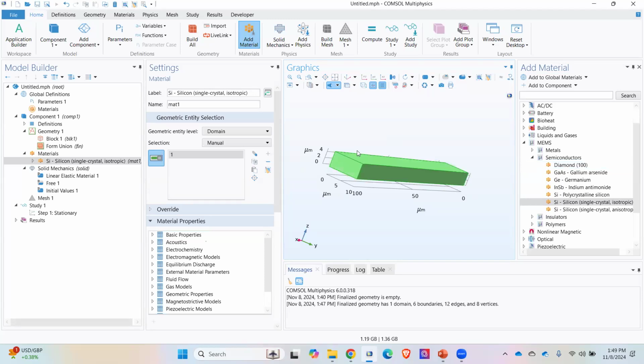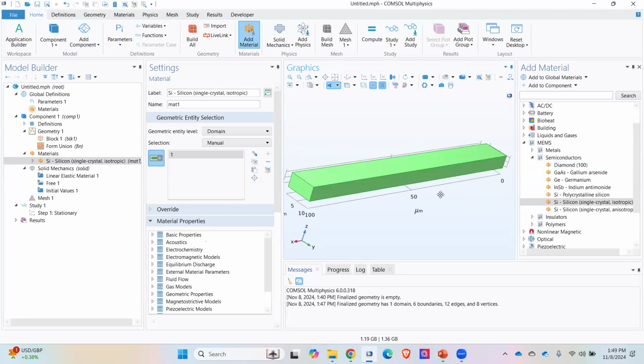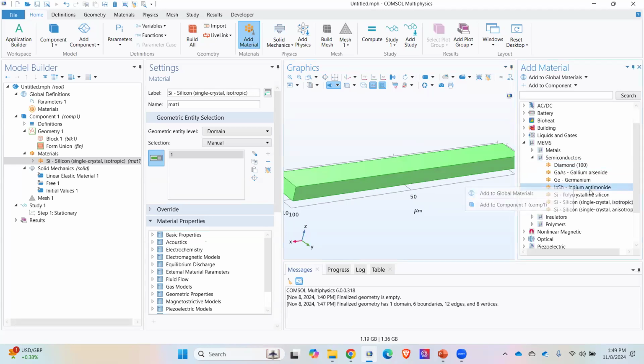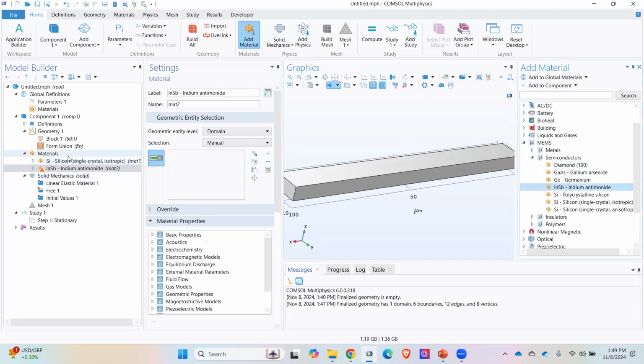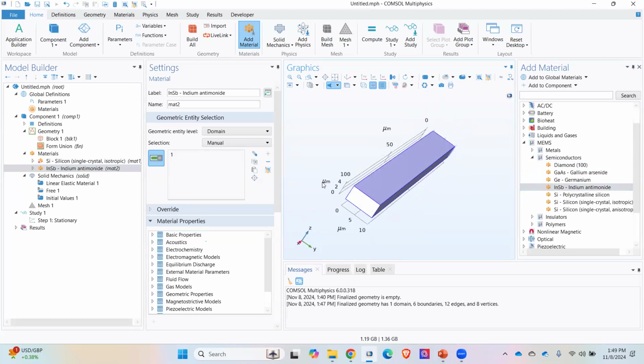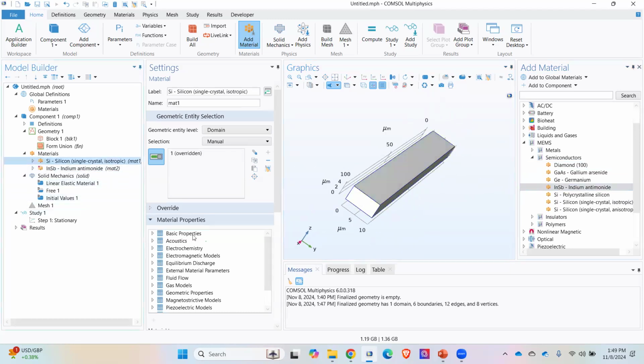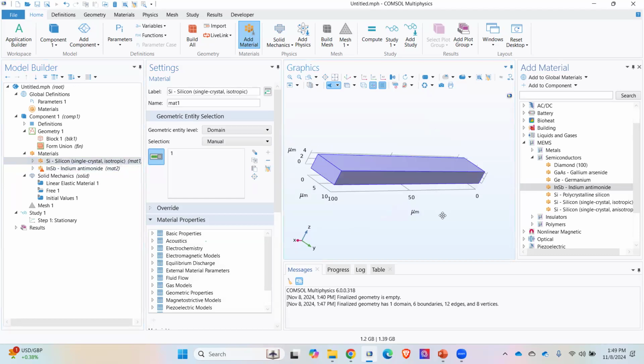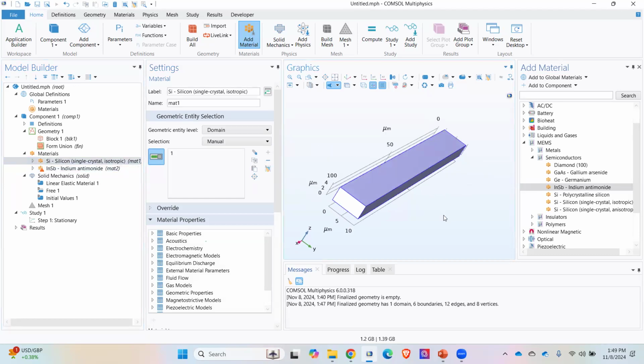If there are multiple designs where you want to put different material properties, you just select the different material. It will come here under materials, and you just click on that, on the particular geometry. Let's say this is my single geometry. I'll just remove this and remove this. I have already assigned this geometry as a single crystalline material.